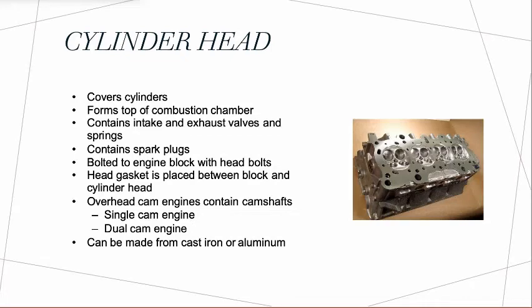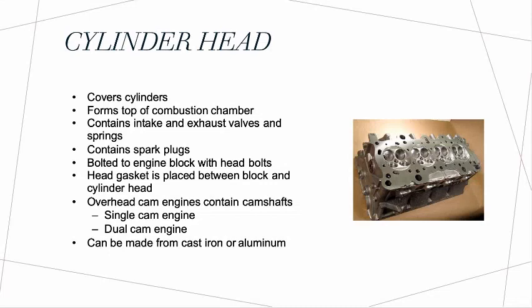The cylinder head also channels the coolant into the engine block, thereby cooling down the engine components. The cylinder head uses a gasket that aids in preventing water or oil from leaking into the combustion chamber. Most cylinder heads are made out of cast iron. A cylinder head made of cast iron is more durable and less expensive. However, cast iron is very heavy and provides lesser efficiency in dissipating heat. For this reason, some manufacturers prefer using cylinder heads made of aluminium, and these cylinder heads are much lighter than cast iron cylinder heads. Performance cars and race cars commonly have aluminium cylinder heads.